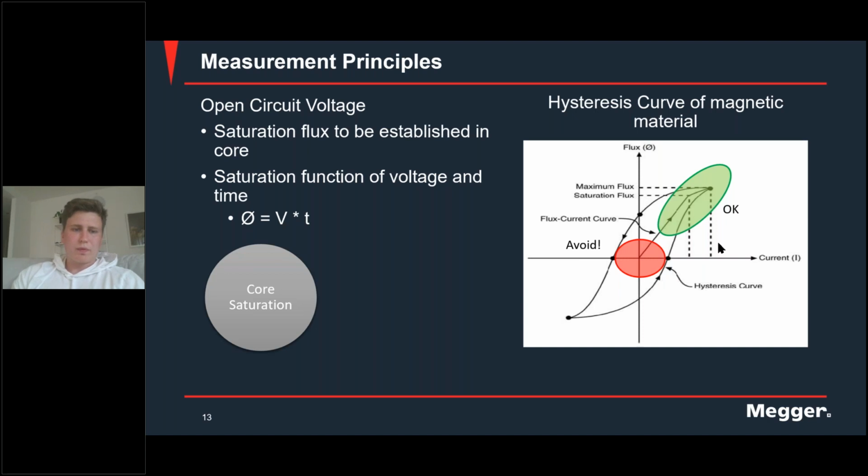I think that just to add to that real quick is that with the process of core saturation, having the core magnetized to the appropriate extent, what you will see on your test instrument would be a reading that doesn't change very often, or it doesn't vary with time a lot. So that's where you can understand that all your conditions have been met, where your current is stable and your core is saturated. So from the influence of high magnetization, what that means is you have a more stable measurement, and because you're achieving that higher magnetization and core saturation, if you follow that technique all the time, it is more likely that you'll get a more consistent resistance measurement.